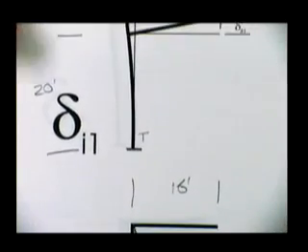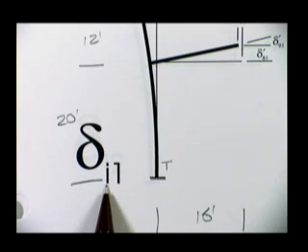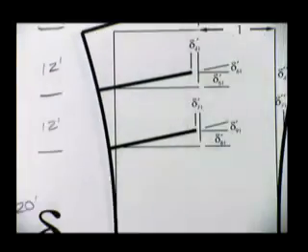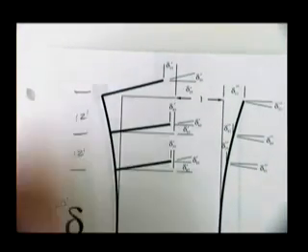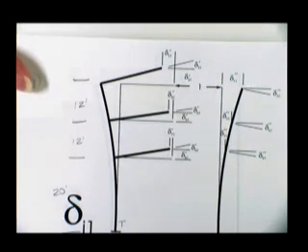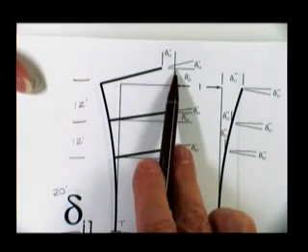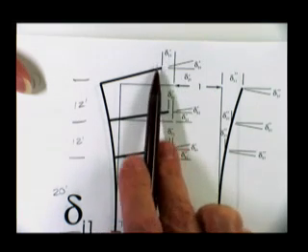All right, as you might imagine now, I need a whole bunch of deltas. First, this is the delta at any point due to a unit load at the number 1 position. You will notice that I have the unit load at the number 1 position. By pushing on this left-hand frame, you move this point to the left, you move that point up, and you cause a rotation of that point.